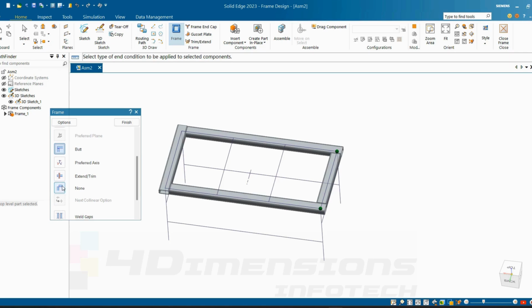If I want to change the preferred condition of the axis, you will get that option. You will get that axis option here also. So I want x axis or else I want y axis. As soon as I click on this y axis, you just need to observe here. This tubing will overlap and the horizontal tubings will get underlapped. So I'll select this y axis. You can see there this is overlapped and these two are underlapped. Again, if I want to change the axis preference, I again go for x axis. It will go as it was earlier.